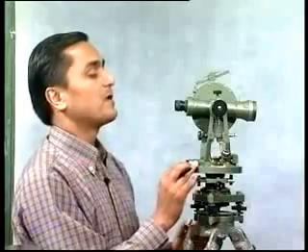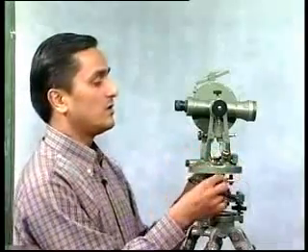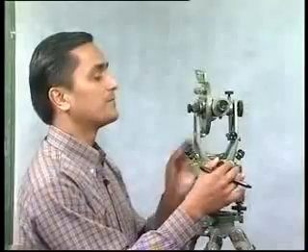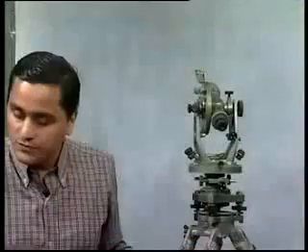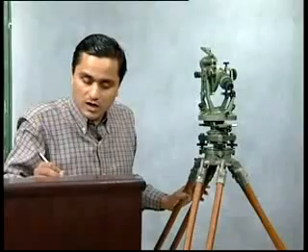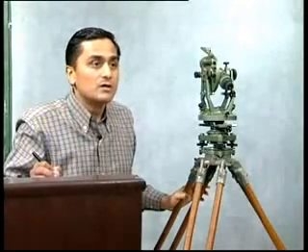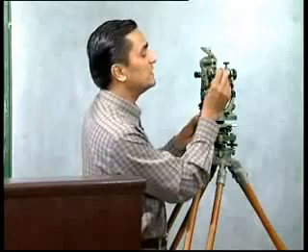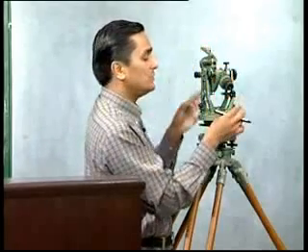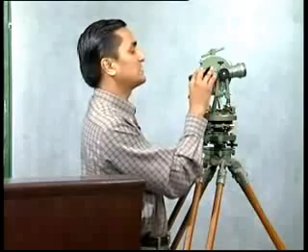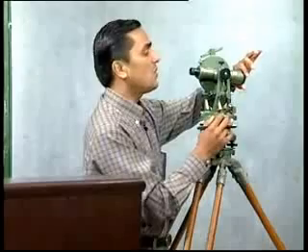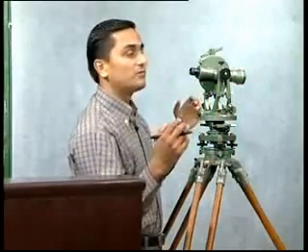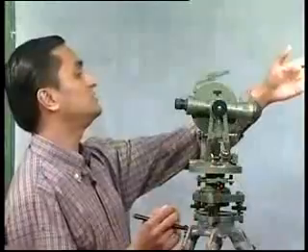Well, along with this, if you look at this telescope very carefully, over here, there is a little V and there is a little I. If I draw it here, what it looks like, there is a V and there is an I. Basically, why do we use it? The V is here and the I is here. We use it, for example, if I need to bisect an electric pole or a ranging rod, the field of view of the telescope is not big. The field of view for a human being is very wide. I can see that ranging rod there.